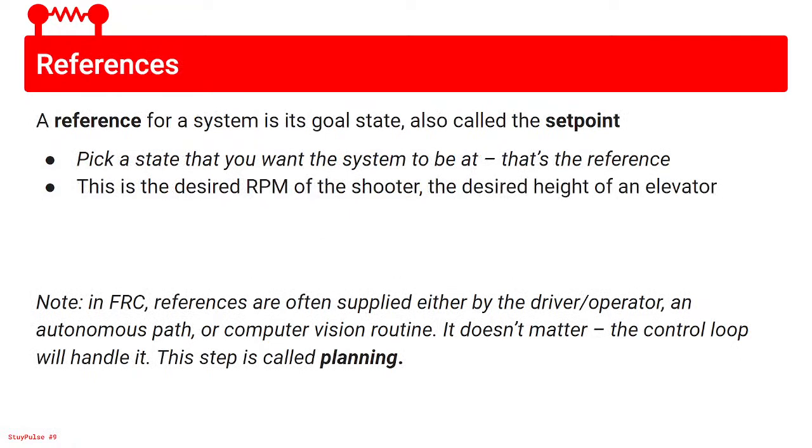So yeah, the reference is kind of like where the human comes into control theory, why it's useful. Picking a reference is just picking the goal state of the system. You pick any state that you want your system to be at. That's the reference. You also call it the set point, right? For a shooter, this is the desired RPM, and for an elevator, this would be the height, right?